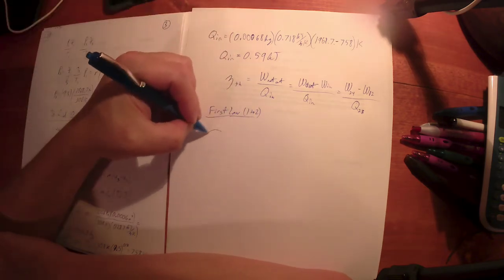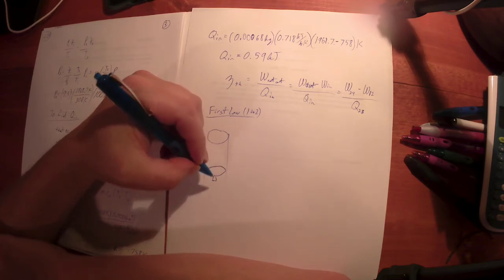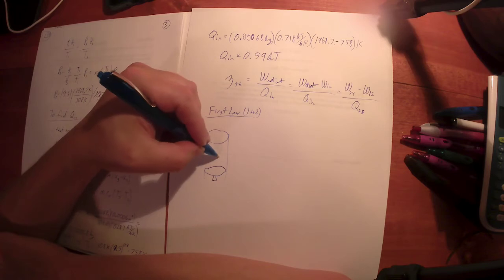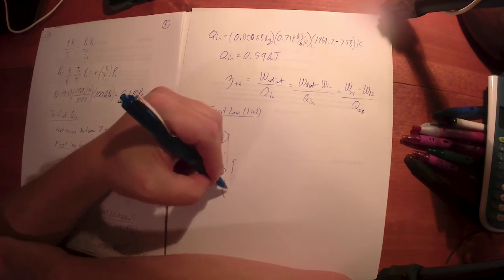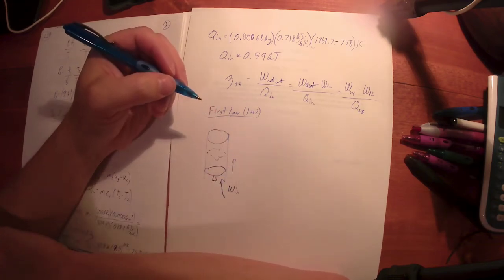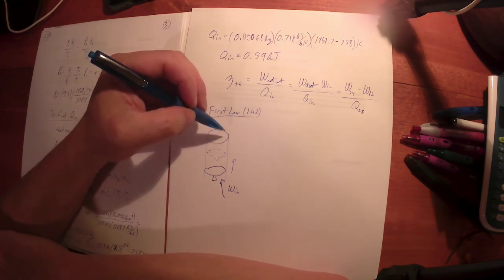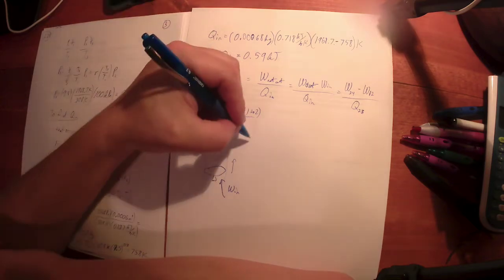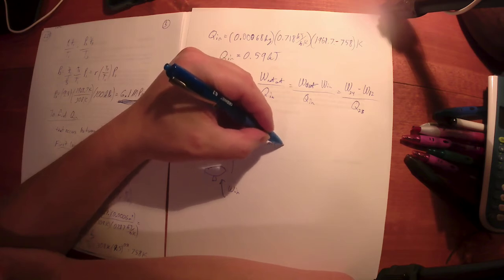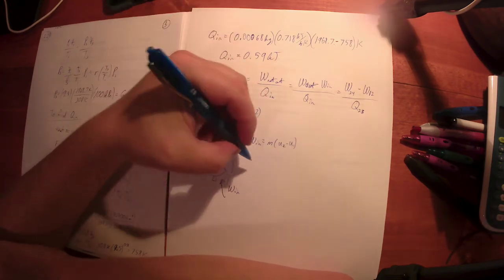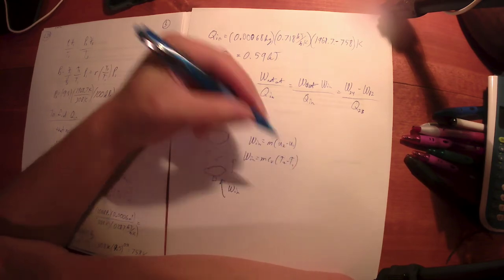First law between states 1 and 2. What occurs from states 1 to 2? Well, again, that's work in, so you're going up here. And to do that, you're putting this work in. It's adiabatic, or at least it's isentropic from state 1 to 2. That means it's adiabatic and it's reversible. They're all reversible. So your work in is equal to, again, it's final minus initial, so it's m times U2 minus U1. So this is work in is equal to m c sub v (T2 minus T1).